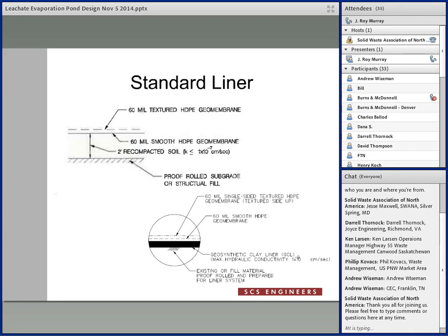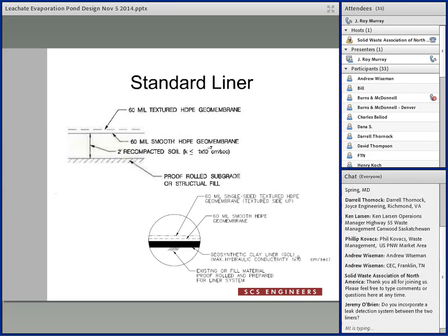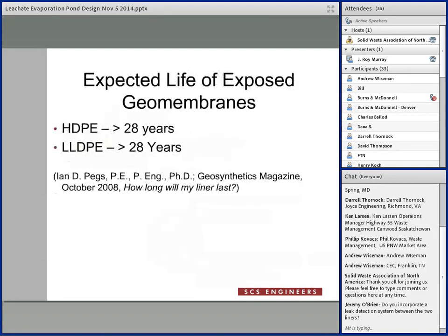All these liners are for facilities that are, in this case, located inside of the landfill groundwater monitoring system. If you do have one outside, then you may have to put in a leak detection layer.